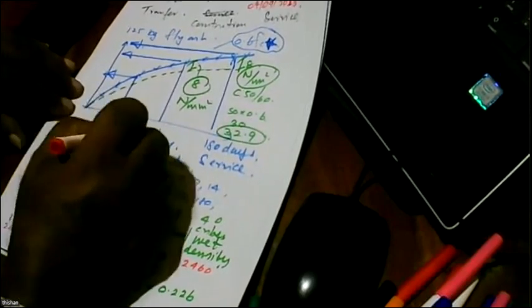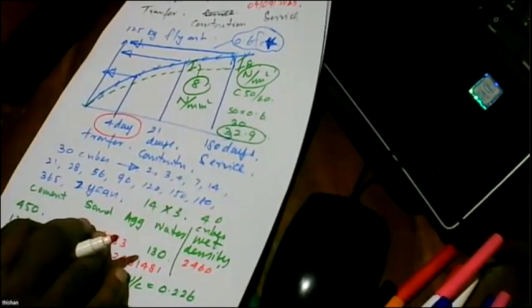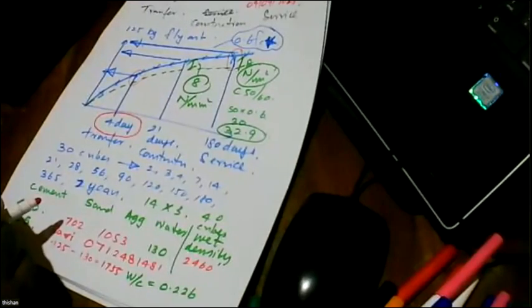And also, you have to be very reasonable with this number: at which day you are going to do the stressing operation, that is, either you apply the stress or cut the tendons. So the age at which you do the transfer is also important. But you can see these stresses, although we are going for a very high target here, need not be very high. Why? Because we have only the self weight of the beam.